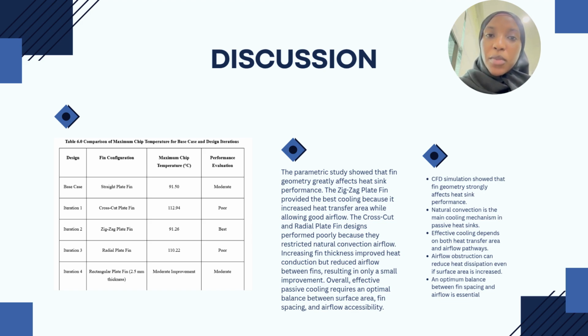I will demonstrate the result and also the conclusion of our project. So as we saw from the report and my friends' presentations, we can say that the simulation showed that the fin geometry strongly affected the heat sink performance, and also that natural convection is the main cooling mechanism in passive heat sinks.